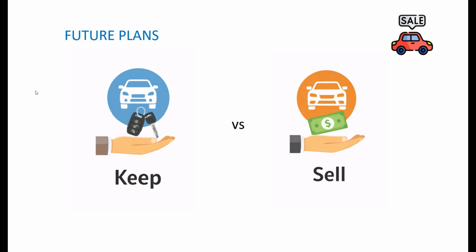Versus somebody who's putting a car audio system in to enjoy it, but ultimately they're going to end up selling the car in a year or two, particularly if it's a new car. So often that will drive you to do more subtle, more OEM type of installs, or make sure that the system is reversible. So you're not cutting big holes and things. You can easily remove equipment and patch things up, so you can return the car back to its original OEM state.